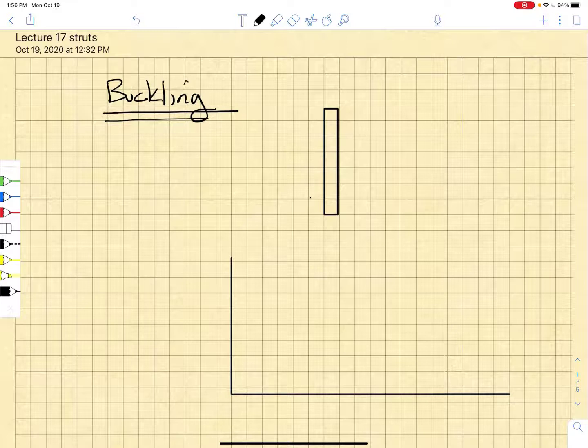In the last lecture, we introduced the notion of buckling failure, where if we have a long, slender column of length L, and we apply a compressive load to that column, then we are interested to know when that load reaches a level at which we get an unstable elastic deformation of this column. It's important to note that buckling failure is an elastic phenomenon. And so we're interested in establishing what the critical load is.